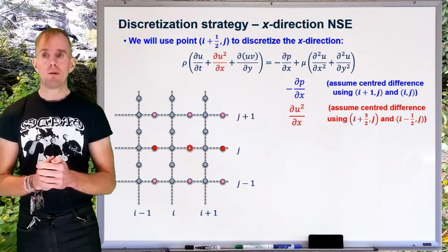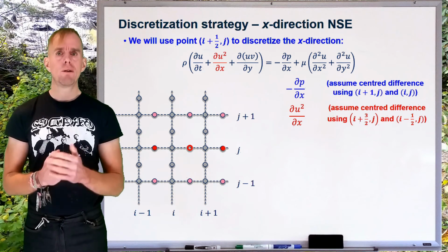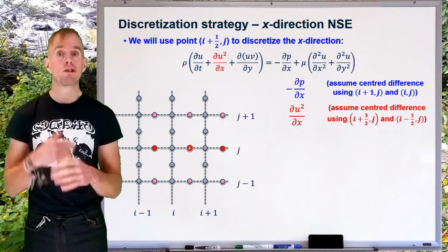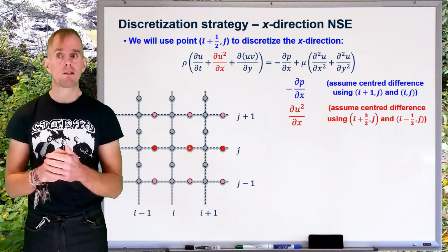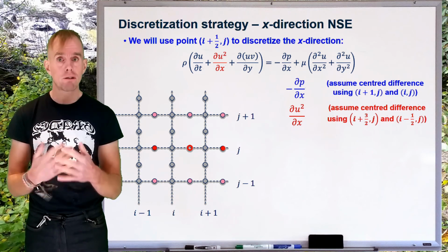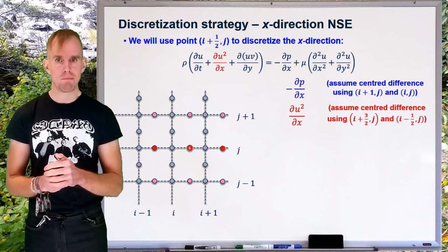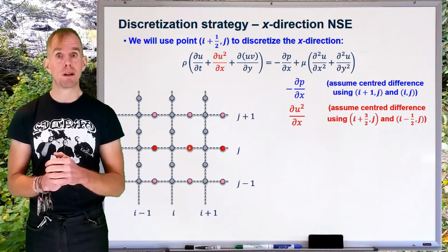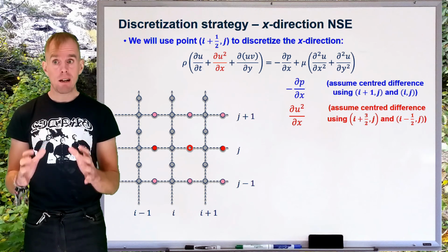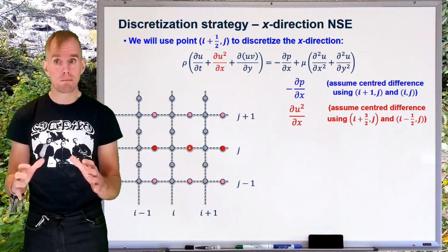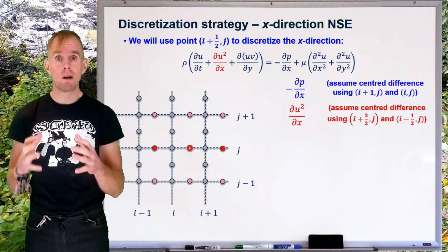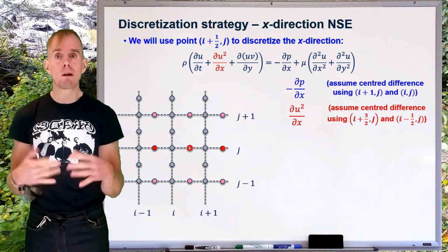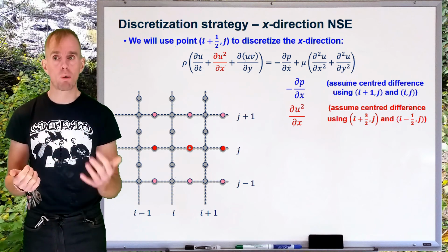Okay, so let's turn our direction to x direction velocities. And let's have a look at the first term that involves x direction velocities spatially, which is d by dx of u squared. So this results, of course, from our convection term, and that u squared came out of the conservation form of the total derivative that we looked at earlier. Now, big disclaimer here, of course, this is convective. You shouldn't be using centre differencing here because we know that information flow is important, and so what we should be using is one of these multi-point upwind difference schemes such as SPUD or QUICK.